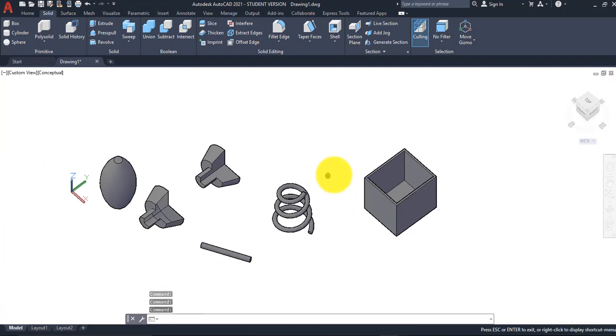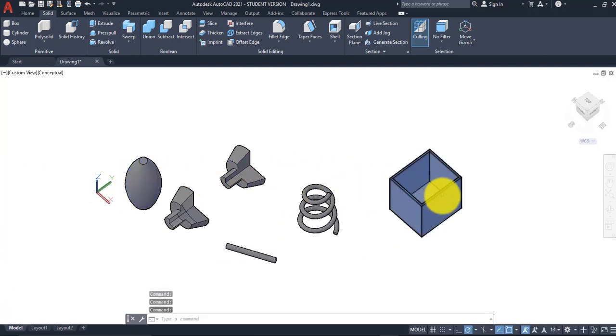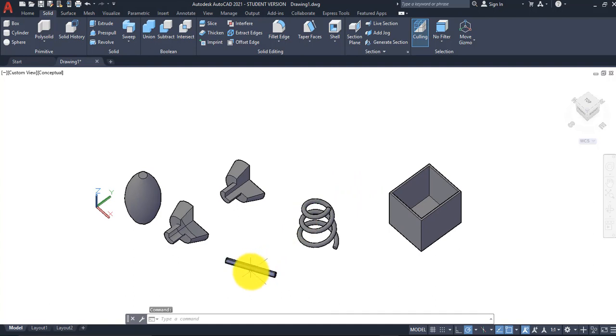So at this point, we looked at these 4 tools, but we're going to set up our paper. It would make it easier for us if we dragged some of these objects apart from each other, so that when we create our viewports in our layout space to set up our paper, which we've done before already in this class, we can have an easier time to find them and crop them.